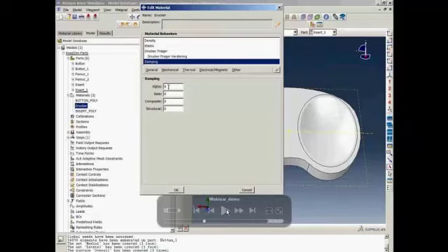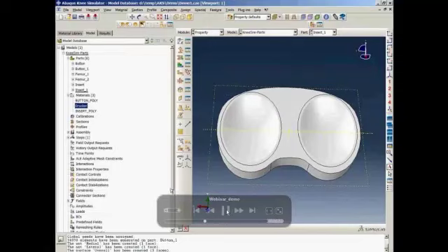Also, because the simulator uses the Abaqus Explicit solver, we recommend the user enter a damping, especially alpha damping, for each material they define. And what we found is that 100 alpha damping is a reasonable number to use for most polymer materials. This is to remove any noise in the solution.